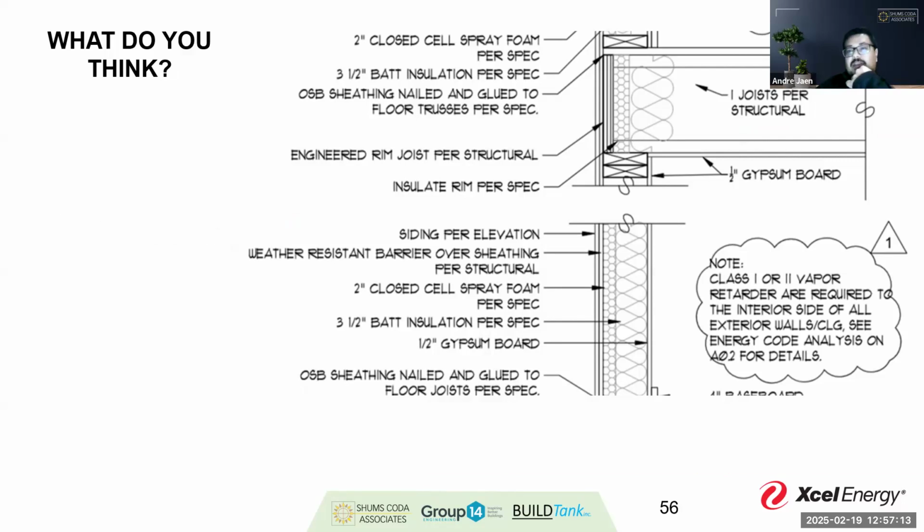Here's another great one where we have an example here of closed cell spray foam in this wall cavity. We have 2 inches of it. Now, 2 inches of closed cell, that's more than 1.5. That meets that requirement for air impermeability.